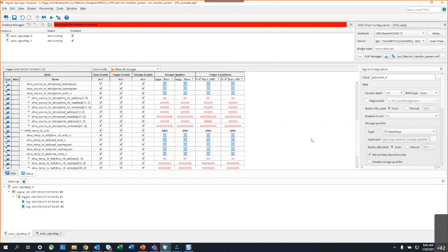So if it says it has started capturing samples, but it won't stop, you can manually stop the logic analyzer, and then you'll be able to see the partially filled buffer. That happens a lot with state-based triggers as well, because you can have the same type of control over when samples are stored in the buffer. If the buffer is not full, the logic analyzer just keeps running.